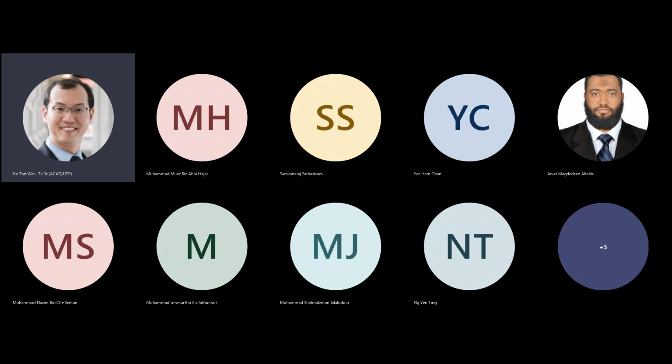You would dope this with N-type material, and this with N-type material, then this may be a P-type block, and then you put a dielectric layer here, typically silicon dioxide. Then there is a conductive layer here. It used to be metal, but nowadays it's actually polysilicon, also a doped silicon layer. And this forms a MOSFET, a metal oxide semiconductor field effect transistor. Very fancy name, but the key point, just as described in the video, is that you apply a voltage here.